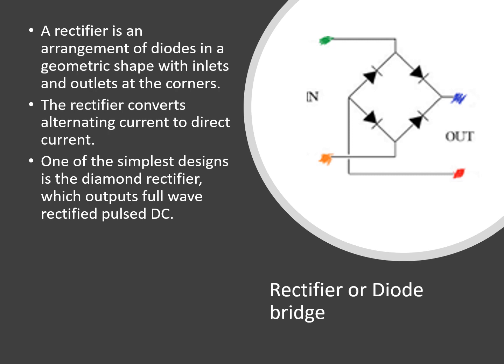Now, let's do the same thing with positive charges. Positive charges coming in from green can only go to the right because of the diodes. Those are one-way streets. So a positive charge heading to the right will exit blue. And let's do orange. Positive charges coming in from orange again can only go to the right because of the one-way streets, and have to exit blue again.